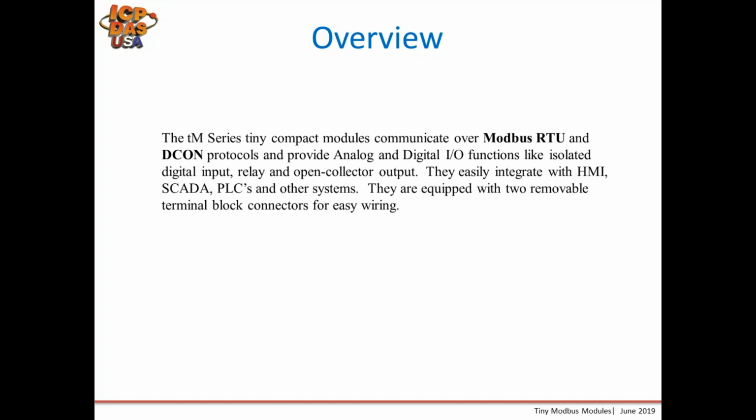They're easy to configure and integrate with existing HMI and SCADA platforms that have built-in drivers for Modbus RTU or an ASCII-based communication system. You also need an RS-485 port, of course, and the PLC would specifically say Modbus RTU. If you need help in determining whether your PLC or existing system can communicate by Modbus RTU, please feel free to let us know, and we'll help you with that.